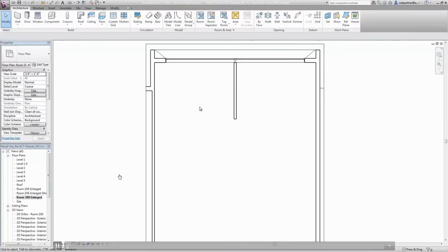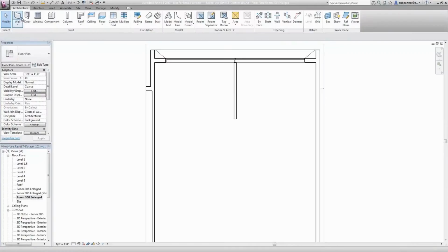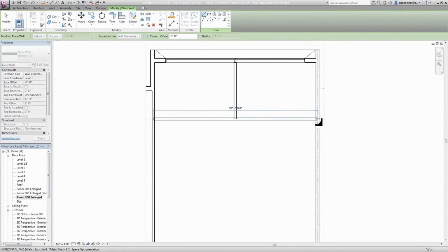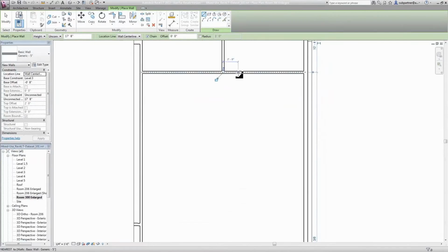So here I have already walls on my building, and now let's do some wall. And you can see I am drawing object, which is the wall, and I have guidelines. So you see the lines which are helping you to position your wall properly, and as soon as you are moving to the wall, you can connect it and draw one wall, and you see that everything has been cleaned up, so you don't have to take care of this. So these walls are correctly connected.